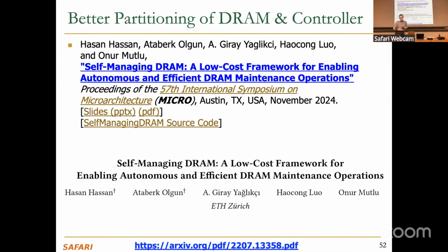Okay, so I'm going to mention one more memory-centric way of thinking about memory. We call this self-managing DRAM. One of the major issues today is that DRAM, for example, is a complete slave to a processor. You have a processor, memory cannot do anything by itself. Processor has to dictate things, right? Meaning, memory cannot even refresh itself, there's a data retention problem with memory. And unless the processor says refresh, the memory cannot refresh things internally, which is interesting, right? So memory has no autonomy. And if you think about this, this is because we have a very processor-centric mindset, right?